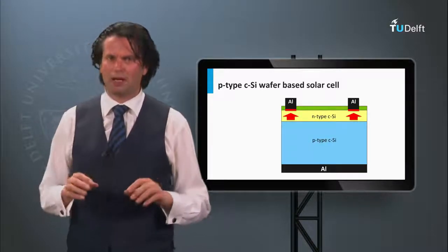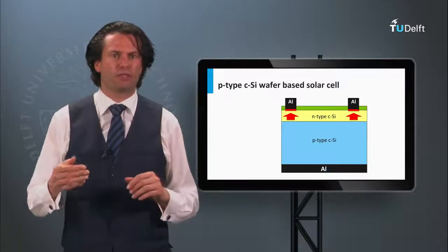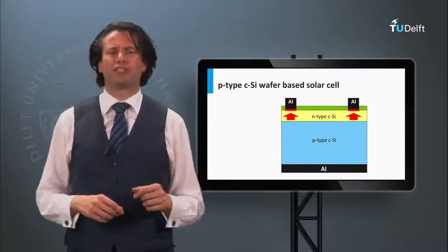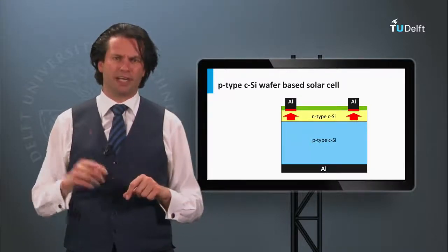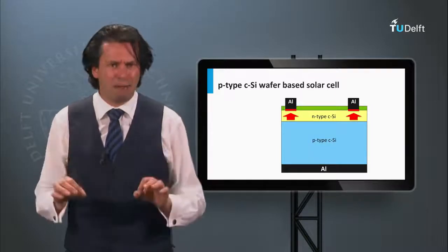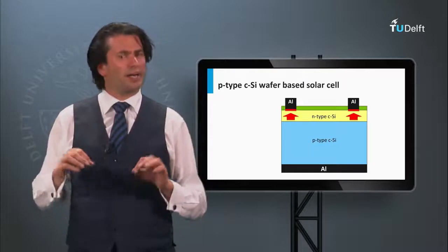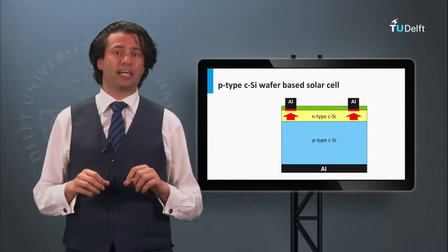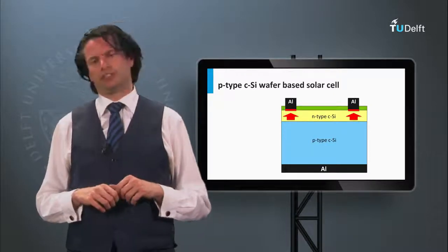In addition, a metal-semiconductor interface induces a barrier for the majority charge carriers. In view of the scope of this course, it's too much detail to discuss this barrier in great detail. Keep in mind that this high barrier will give rise to a higher contact resistance. Again, high doping levels can reduce the recombination velocity at the metal-semiconductor interface and reduce the contact resistance.